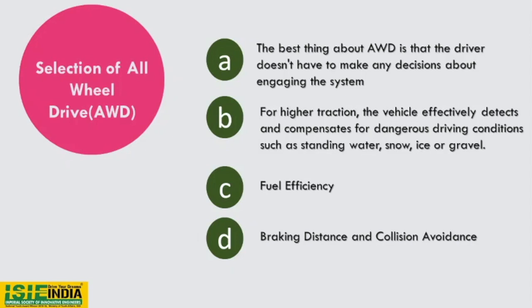Therefore, we can say that all-wheel drive is available on a wide variety of vehicles, from compact sedans to performance models to all sizes of SUVs also. Therefore, if we look at the traction distribution, the rear wheels engage when the sensor detects slippage from the front wheels, meaning that it only engages when there is a need. Therefore, it is saving fuel here.